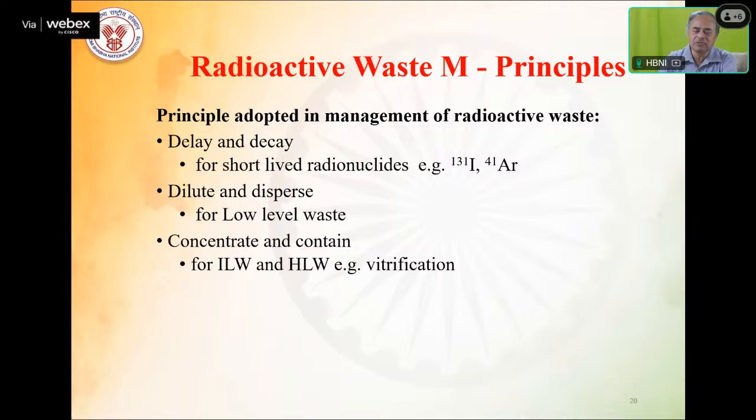Now, the principles of radioactive waste management. The principles adopted for waste management. The basic three principles are there. That is delay and decay. There are some short-lived radionuclides like iodine and argon.